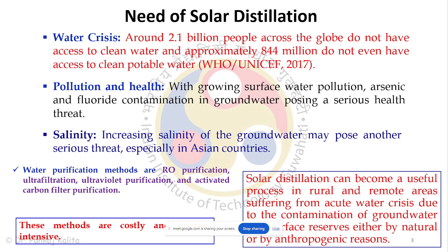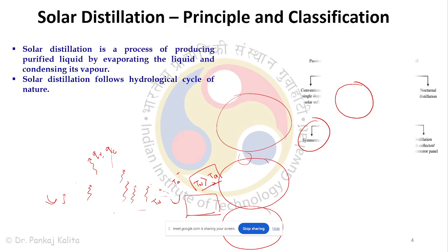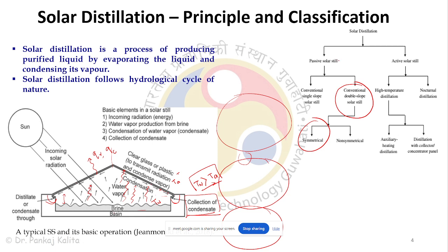Solar desalination is one of the methods. If I just summarize it for you, it's similar to your water vapor cycle. You have some saline water, or it can be contaminated water. With the help of solar radiation, we heat this water, the water evaporates, and it gets condensed on this glass surface as it rises after heating, then trickles back here, and we collect this distilled water.